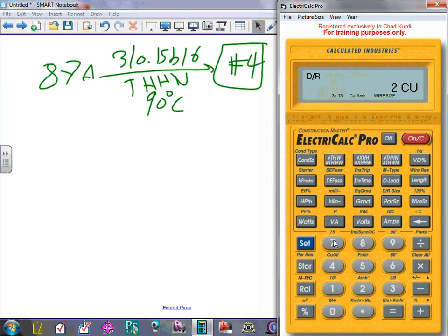Now we're sizing based on 75 derating. We are sizing derated cables based on 75. Piece of cake. Does that make sense, guys? Because sometimes if you have THHN/THW, most of the installation has THHN/THW. So if the whole scenario here is 60 degree, and the 9 conductors in one conduit sitting on the roof, could it be? Easily.